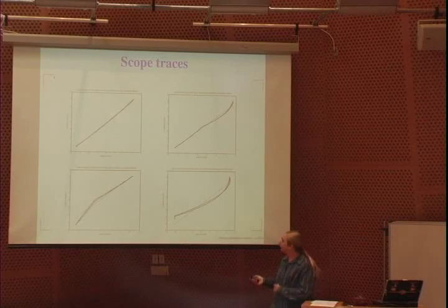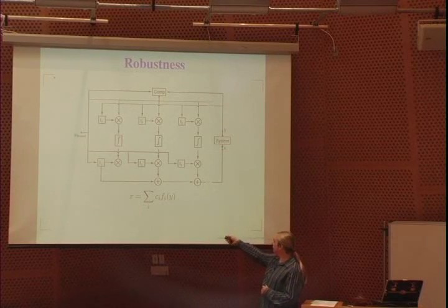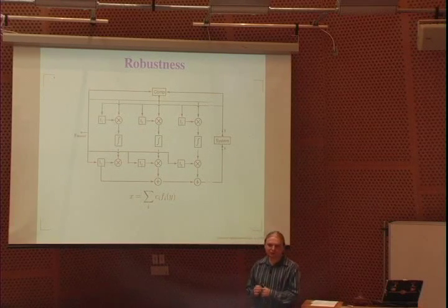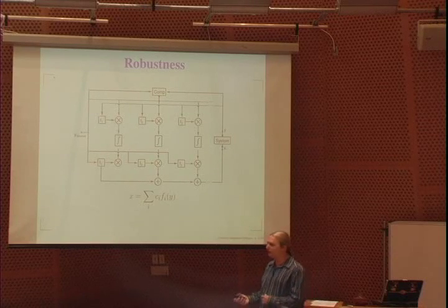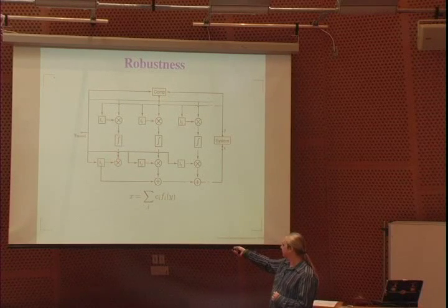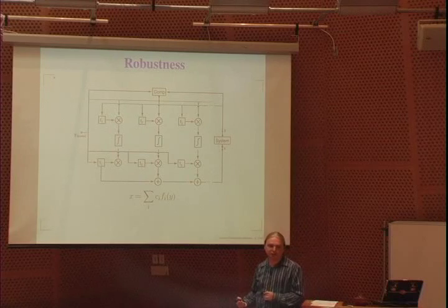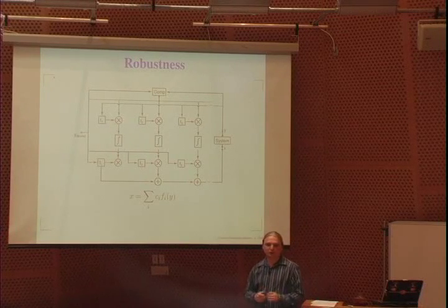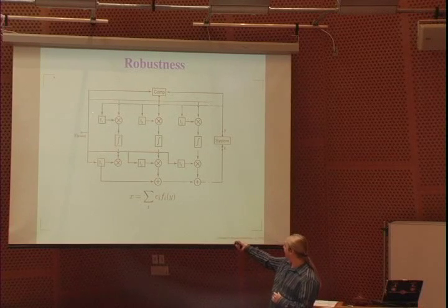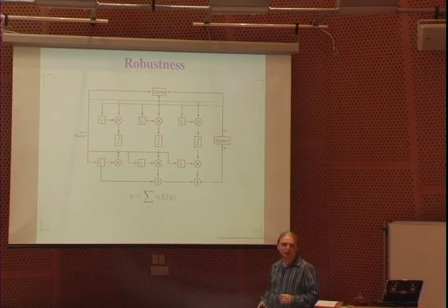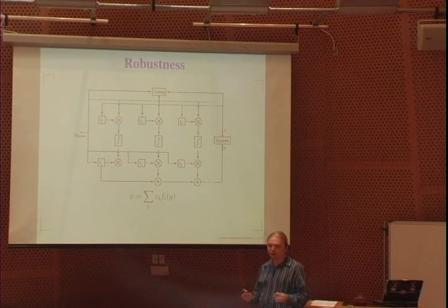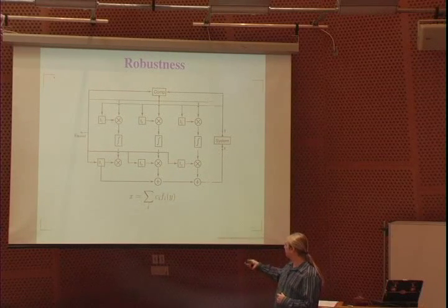This circuit in a more generalized form, the way that it looks is I have a column for each term of this model. Let's say that I was to build this in an integrated circuit, build a complex system like this that had, say, 100 columns or a large number of columns. These columns are pretty easy to build. These multipliers, you can just use a Gilbert cell for. They don't actually need to be very good. Only performance around the origin matters a lot. Otherwise, the error that you get from that is pretty small. These functions need to match, but if they're not very well implemented, it's just going to build a model with a different set of basis functions, but the model will still be pretty good. So this is actually a pretty simple circuit to build.